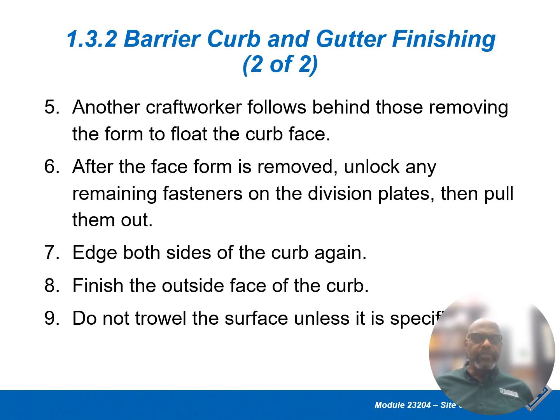Edge both sides of the curb again. Finish the outside face of the curb. Do not trowel the surface unless specified. Usually the curb is a rough surface, typically not very smooth, again for reasons of traction.